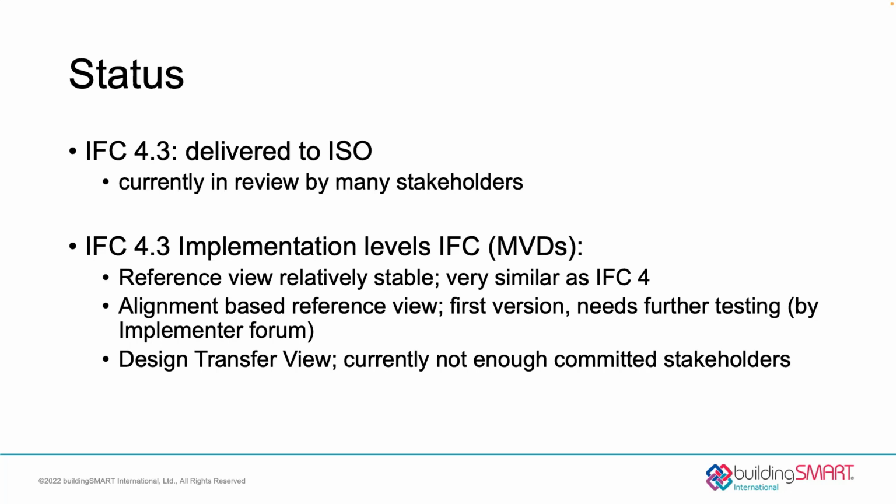we still see IFC2X3 files, right? Because of what people know. It tends to have broader support. A lot of people are used to still doing those and not even IFC4. That's improving a bit now that there are more and more tools that have actually certified on IFC4, so there is that to look forward to. I think we're going to end up in a situation where we're going to see IFC2X3, IFC4, and IFC 4.3 files floating around simultaneously, because IFC2X3 is still considered an official supported standard.